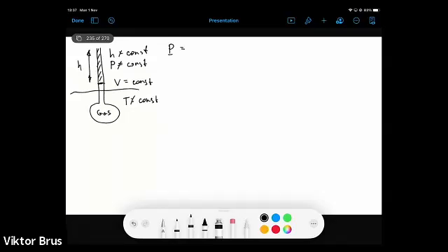We consider pressure which is equal to P naught, the pressure at, let's say, 0 degrees Celsius as some reference temperature, plus the change in the height of the mercury pillar. So it will be rho, the density of this liquid which keeps the gas inside, times g times delta h. So that will give us the pressure inside.